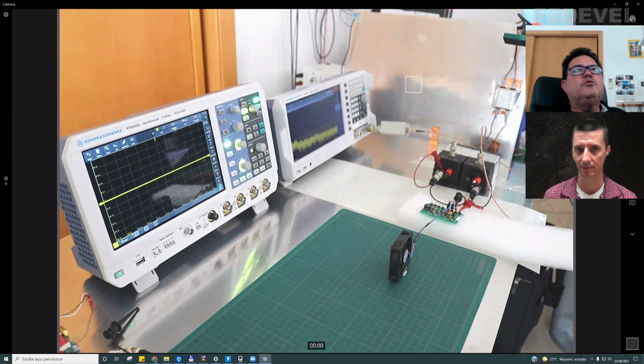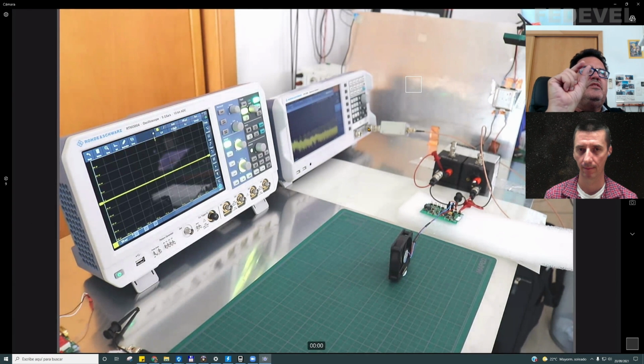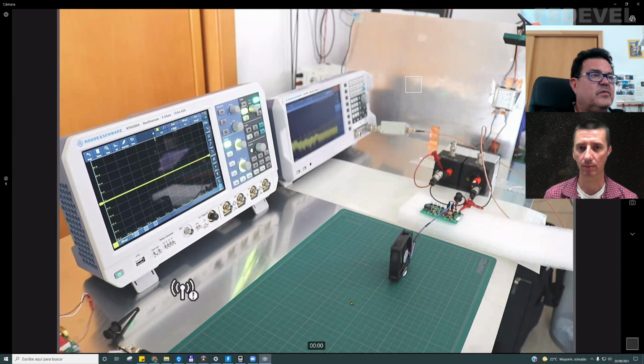But a spectrum analyzer with a very high dynamic range has internal circuits with amplifiers or mixers that are prepared to work with very small signals. So usually the maximum signal you can apply at the connector is very small, and this is why you use this kind of protector. So why don't they build this protection inside the spectrum analyzer?